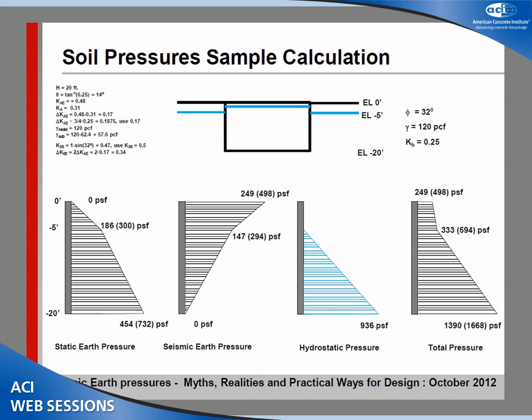The same thing for the dynamic case, and notice here that practitioners, engineers, normally consider that the dynamic soil pressure follows a distribution that is kind of inverted from the static one. This is after, in the 70s, Seed and Whitman said that the dynamic soil pressure distribution should be acting not at 1/3 from the bottom, but at 1/3 from the top. And that's actually also the same recommendation that this committee has. However, experimental results are against this, but this is what we use in practice.